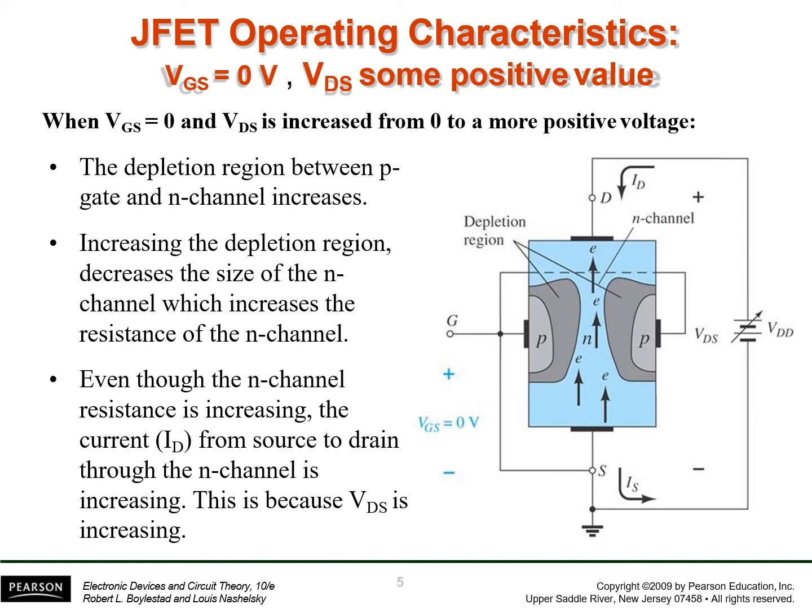As we go on increasing this voltage, the current from the drain to the source increases, but along with it, the depletion regions between the P and N type materials on both the sides go on increasing, and a point comes when both of these depletion regions combine.